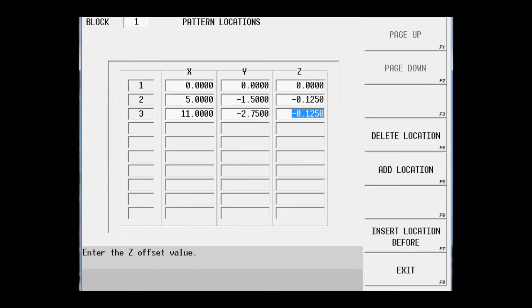That leaves us with one last part, which is going to be the 5 inches in X plus the 6 inches plus the additional half. So we have 11.5 inches. The last position we used for Y was minus 2.750, and we see that this part is 5 inches in the positive direction from that, so we simply put 5 inches plus enter.